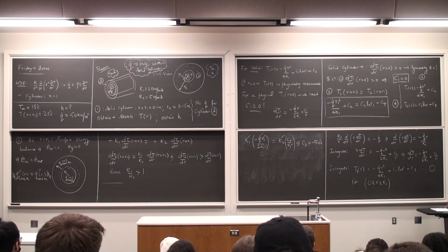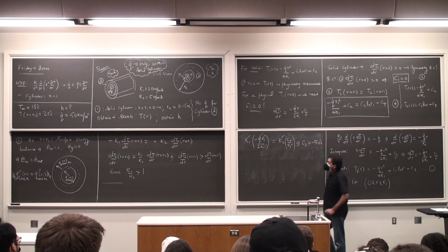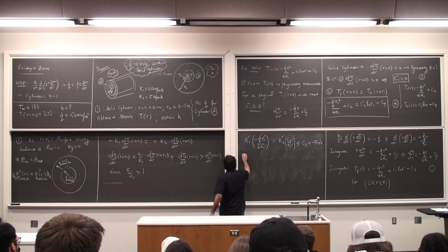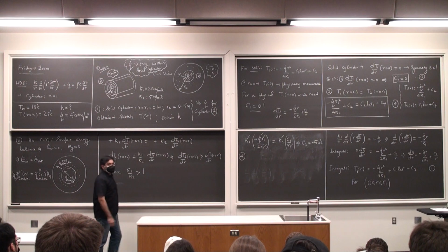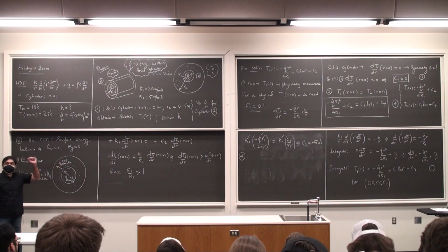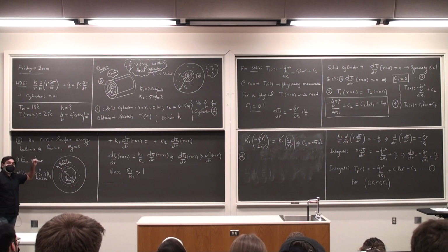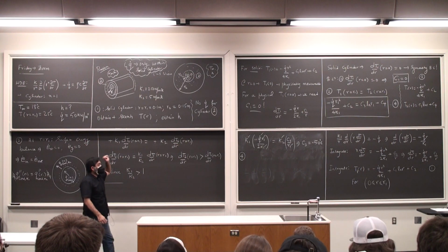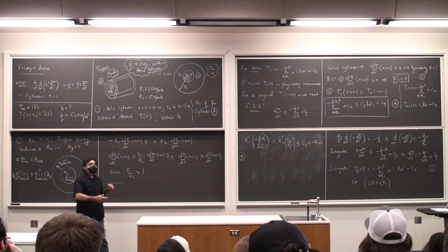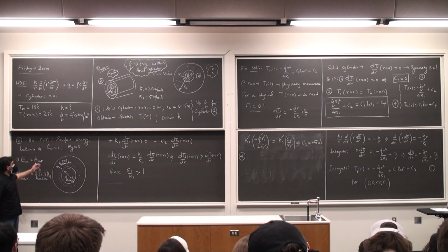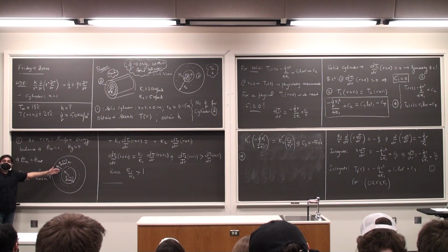Okay? Fourth equation. First equation, center line is insulated. dT by dr at R equals 0 is 0. So we made use of that. Then I made use of the fact that T1 and T2 at R1 is the same. Then we made use of the fact that there is energy balance taking place.